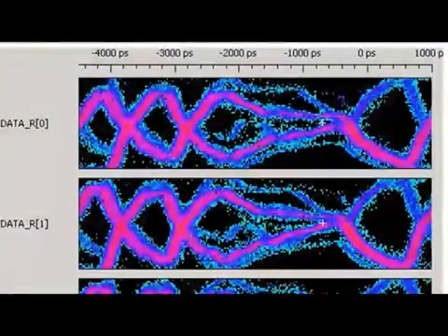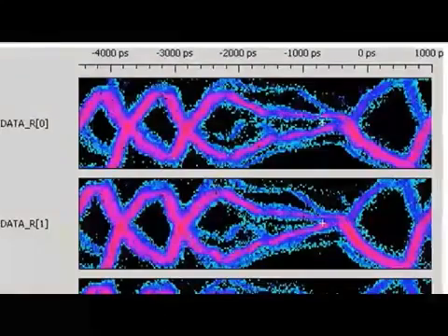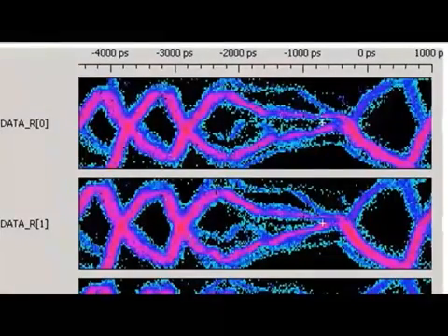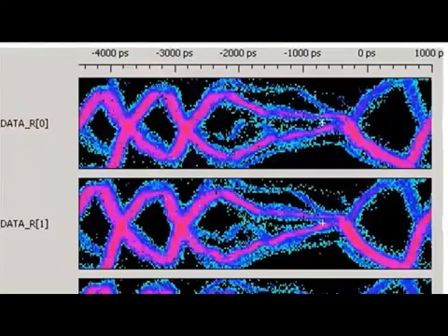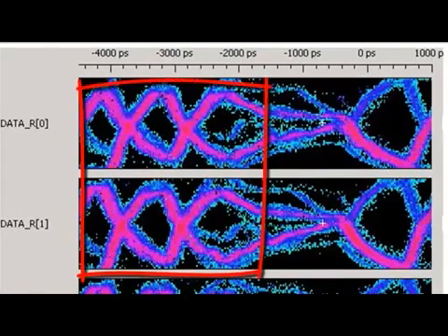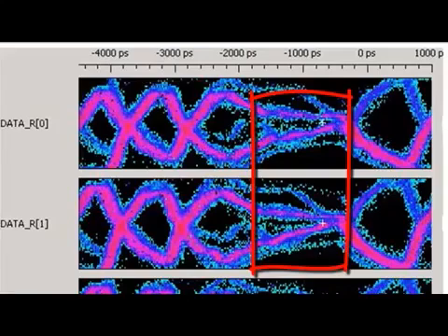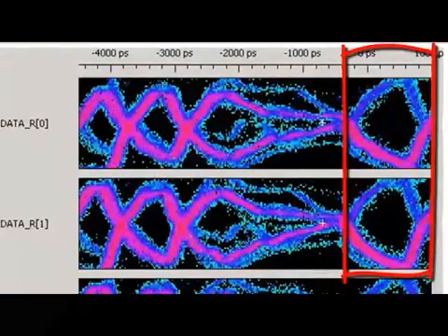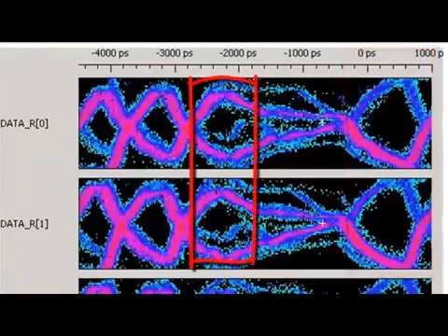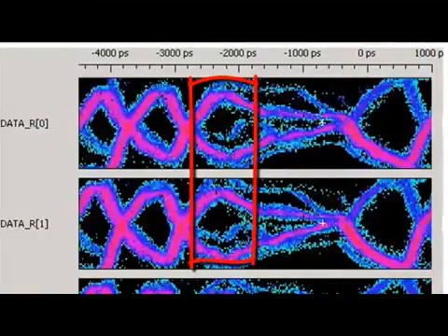Bubble bursts can be problematic as it requires the termination to be released and then controlled again within 1 clock cycle. In the example shown, we are seeing the 3 last samples in a read burst, followed by 1 clock cycle where the data termination was released and tri-stated, and then another cycle where the next read burst to the same rank began. Note that the last sample in the first burst is collapsed.